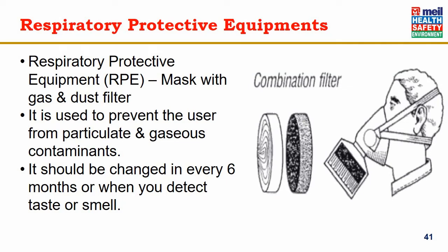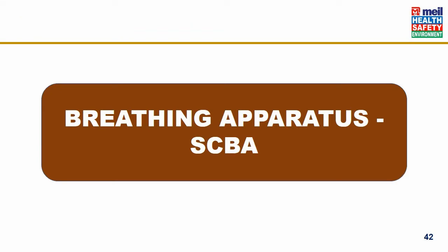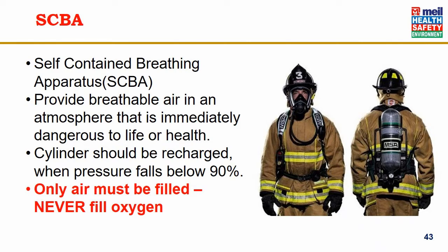Breathing apparatus, self-contained breathing apparatus, provides breathable air in an atmosphere that is immediately dangerous to life or health. Cylinder should be recharged when the pressure falls below 90%. Only air must be filled. Never fill oxygen in a SCBA equipment because it can create serious fire hazards.